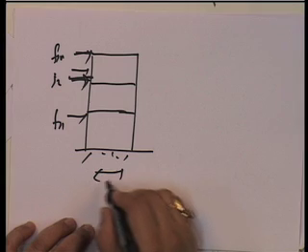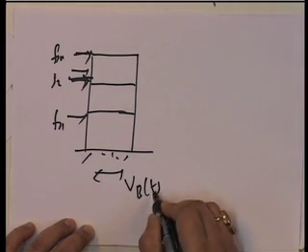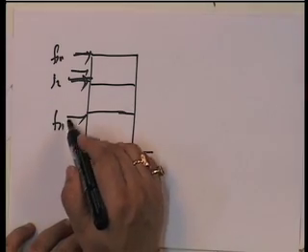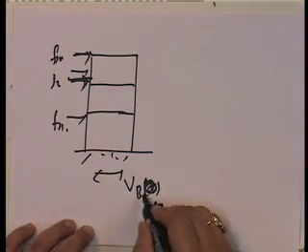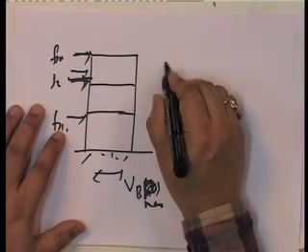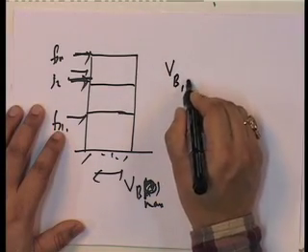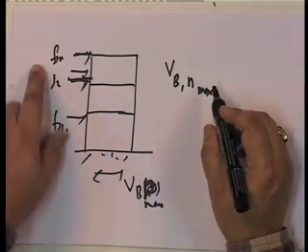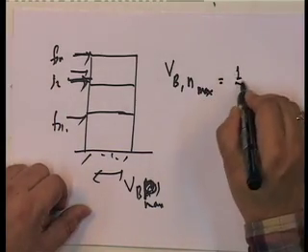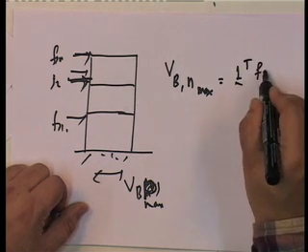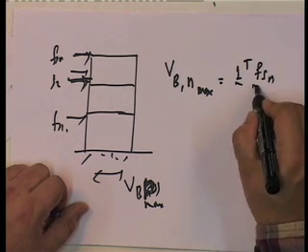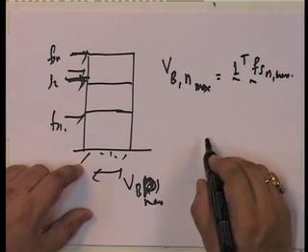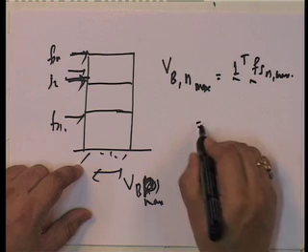So if I look at the base shear, or rather not time, the max, because these are all in the nth mode, this is going to be the base shear in the nth mode, and obviously maximum. Okay, what is that going to be equal to? That's going to be equal to 1 transpose into Fsn max.